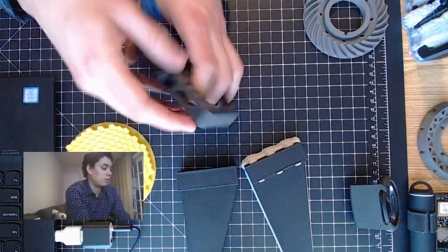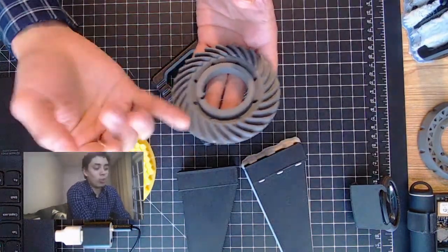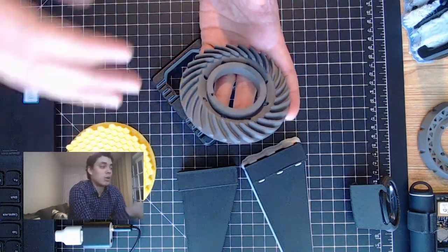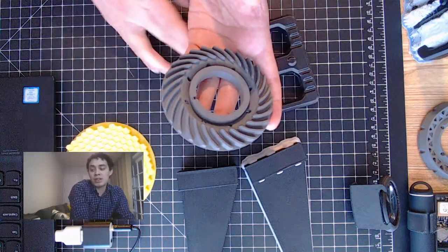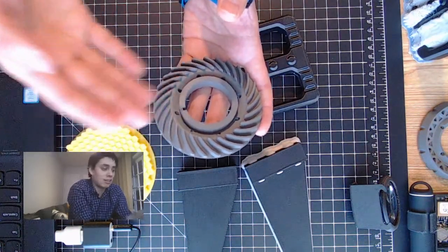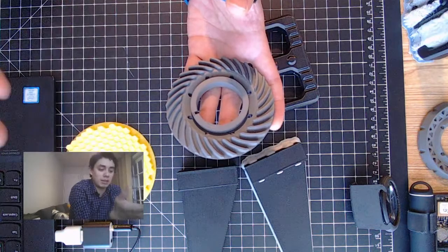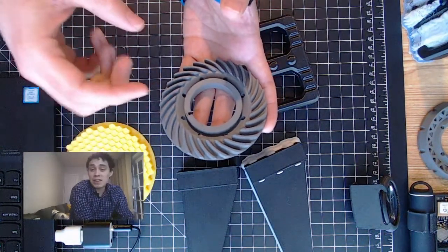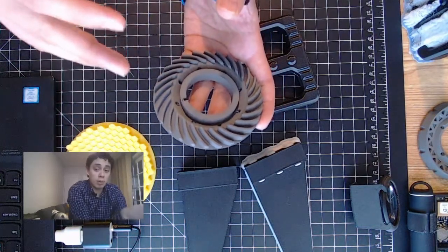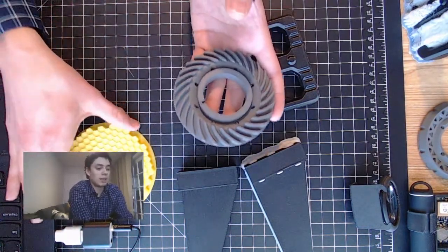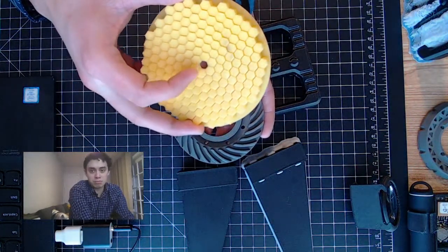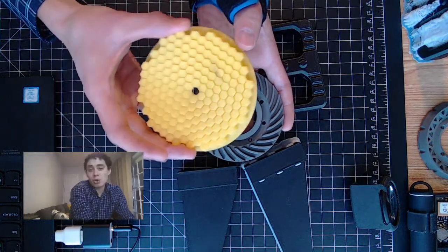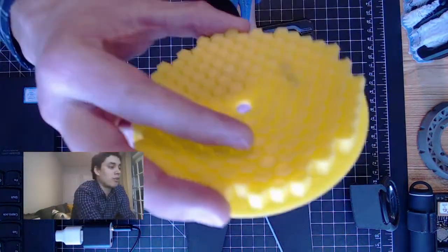Is the final part super shallow and does it have a lot of detail? Therefore, I would rather orient those layers against that detail so that it's actually allowing me to describe it in many more layers as opposed to just a few. So that's the final consideration. Not all of the parts will have all of the considerations, right? In this case, this is just a demo part. It's just a model, so I don't really care about loads being applied, but I would probably care about the look of the part, right?